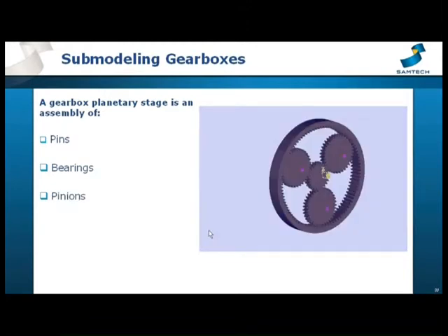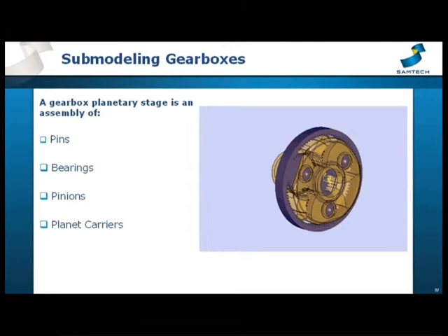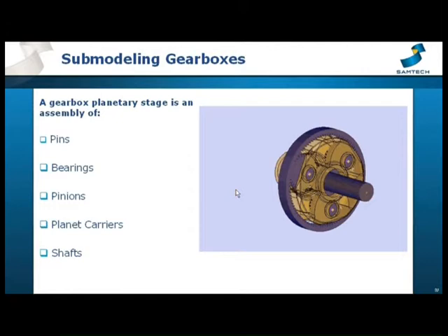Then pinions are defined using the macro with the pins as support. Next, the planet carrier superelement can be added and linked to the pins. And finally, both the input and output shaft can be added.